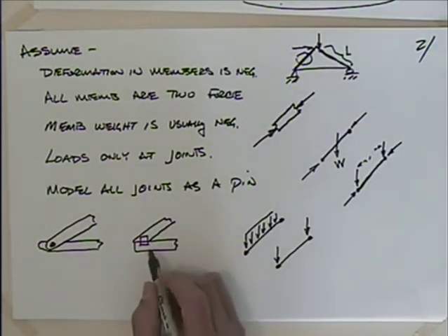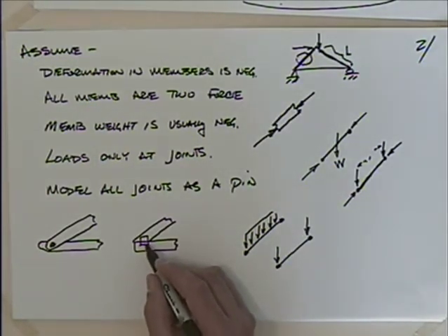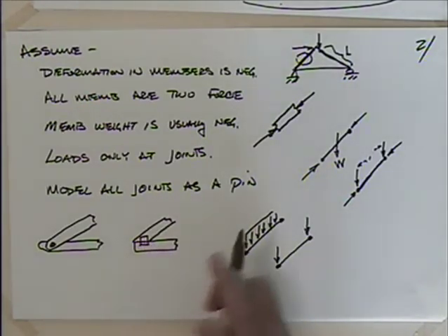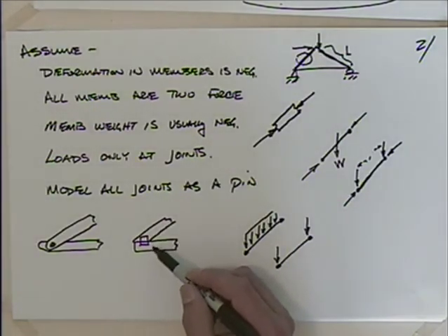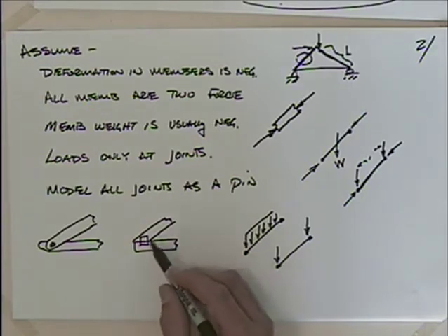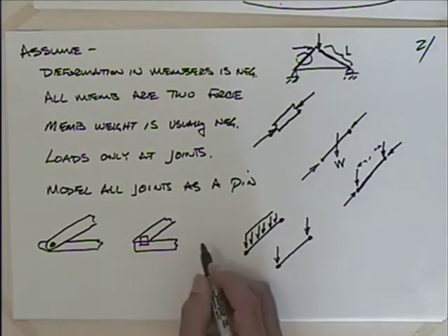So from a fire standpoint, it's a bit of a problem. They don't hold up as well as other methods in a fire, because actually metal weakens quite a bit when it's exposed to heat, whereas the wood just kind of chars, and that process takes a while. So this has some disadvantages based on other things, but you can still model it pretty well with a pin.